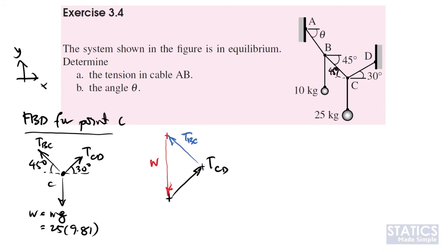If you look at the direction of the arrows, it will make a loop. It can be clockwise or counterclockwise, it doesn't matter, but it will be a closed loop. This is different from a resultant problem, which will not be a closed loop. For example, F can be decomposed into Fx and Fy. If I draw the triangle, you have Fx starting from this point, and then you add Fy.